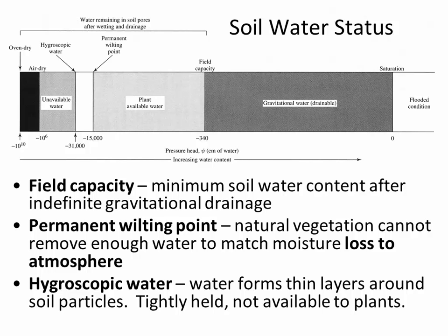Okay, back to soil water. Equally important, less dramatic. Okay, so we talked about field capacity, wilting point. One of the things we haven't mentioned so far is hygroscopic water. And what that is, that's the water that's around the edge in the voids, and it's very tightly held. It is the water that's just forming a small membrane in the soil voids.